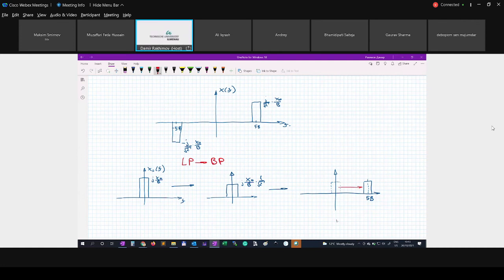Because in our case, we have a pure imaginary spectrum in the low pass range. As a result, we have to move it to the negative range with negative amplitude. So we place it at frequency minus 5B, and then we revert the amplitude to minus J x0 over B times 1 over square root of 2.